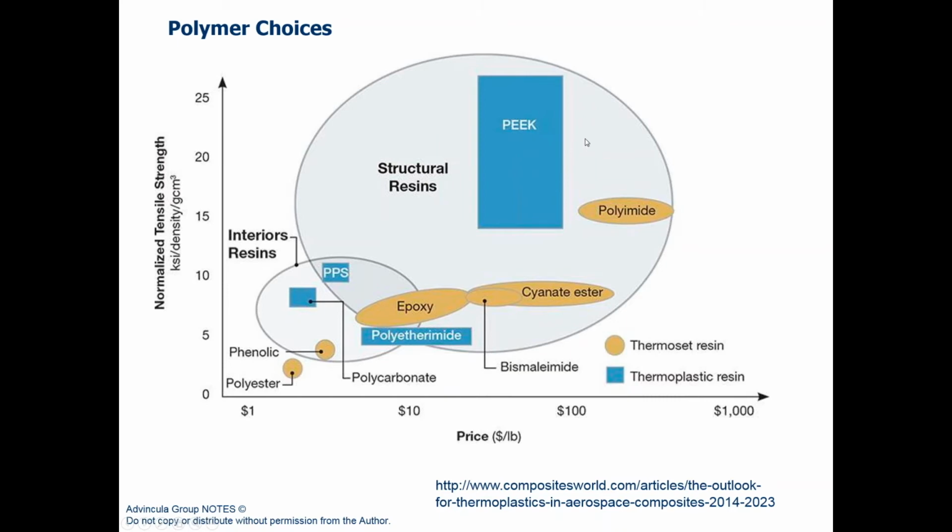As you can see here, the cost almost tracks the increase in normalized tensile strength. So 3D printing, in order to be useful for a variety of applications in, let's say, the automotive parts, tooling industry, or aircraft industry, has to reach the performance of high tensile strength, such as PEEK. Ordinary plastics like polyethylene, polypropylene, ABS, or PLA have limitations in that they cannot be used for higher temperature or high thermomechanical applications. But let us review some of the traditional fabrication methods.